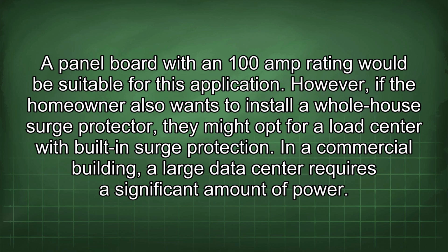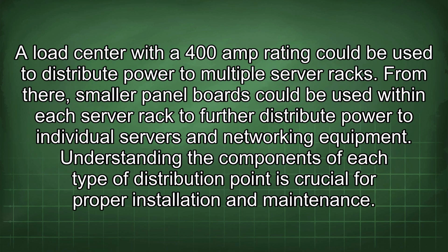However, if the homeowner also wants to install a whole house surge protector, they might opt for a load center with built-in surge protection. In a commercial building, a large data center requires a significant amount of power. A load center with a 400 amp rating could be used to distribute power to multiple server racks. From there, smaller panel boards could be used within each server rack to further distribute power to individual servers and networking equipment.